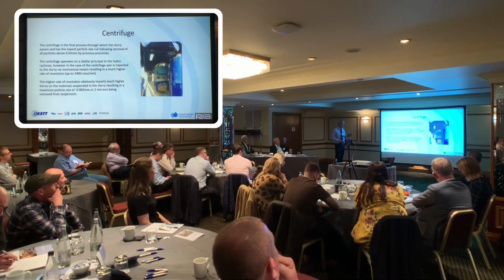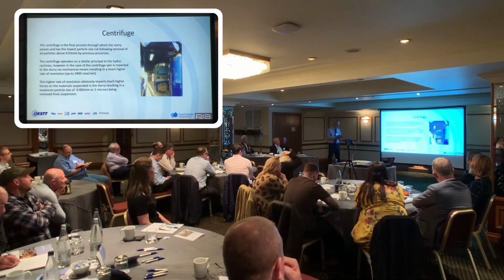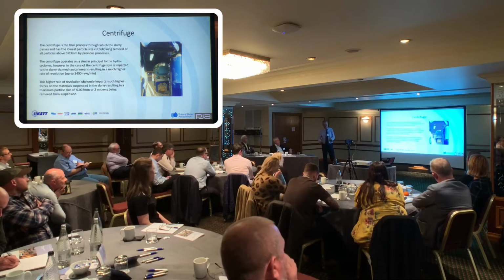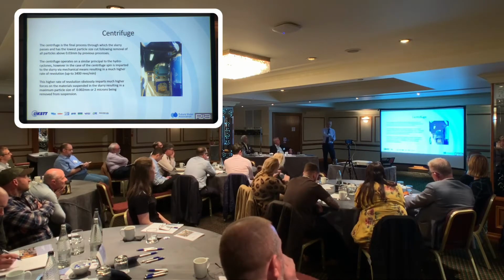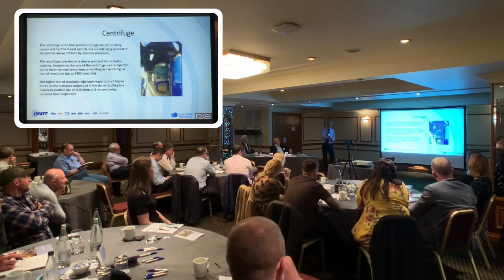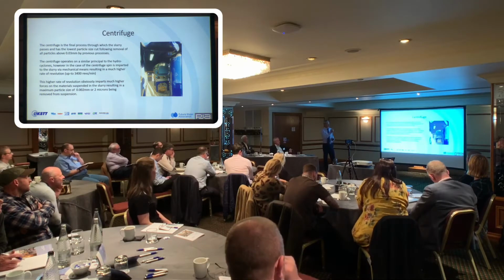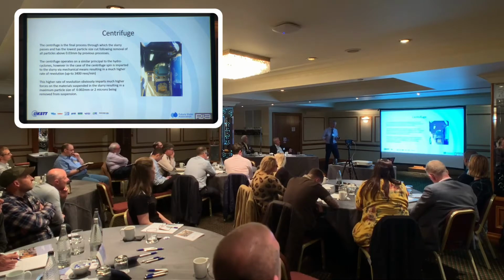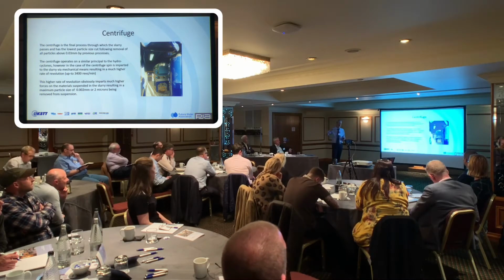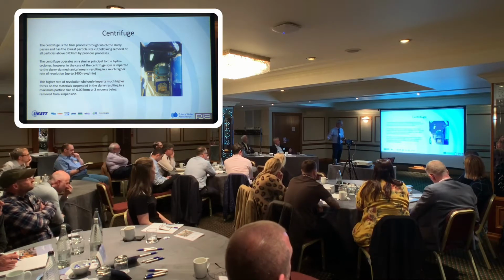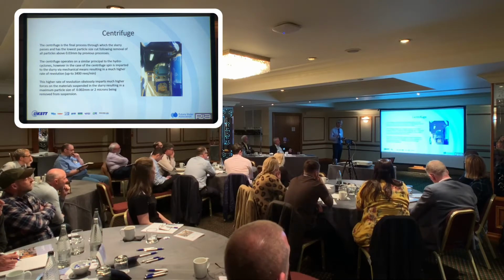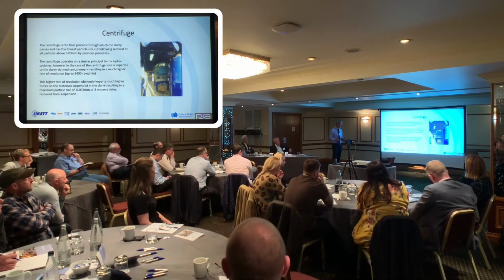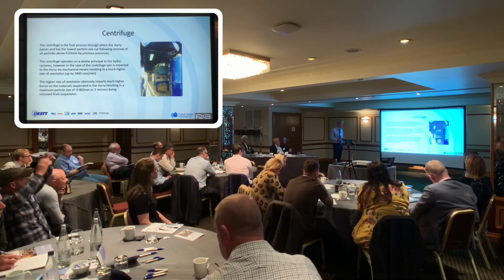Centrifuge. So all of the other processes I mentioned earlier are in line, so that the whole flow goes through the coarse screen and the whole flow goes through the cones. But when you get to the centrifuge system, this is an offline system, so it is constantly running in the background, taking out small sub 3 micron kind of particles and below.